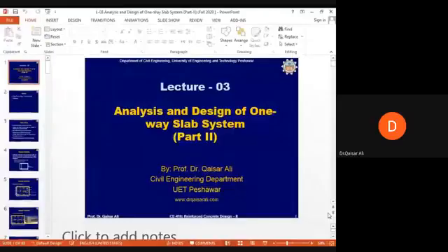No, the flexure reinforcement has nothing to do with the shear reinforcement. You have to clear this concept, okay? If there are 4 bars in the midspan, this is very obvious, very clear and very logical, because midspan is subjected to maximum bending moment, so it should have 4 bars. That is correct. But why are these bars curtailed, reduced, towards the support? Again, this is very logical, because positive bending moments are very small near the supports. If you draw a bending moment diagram,